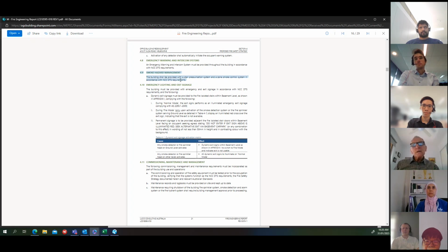Happy days. But also there might be a project that's less than 25 metres high. It might be a school or a hospital, where there's a lot of people, and again, their safety is paramount. So they might say this building's only 2 stories high, but we believe that stair pressurisation is required for whatever reason. And if they put that in their fire engineering report, that's part of the documentation for the project, and we have to do that. Okay.